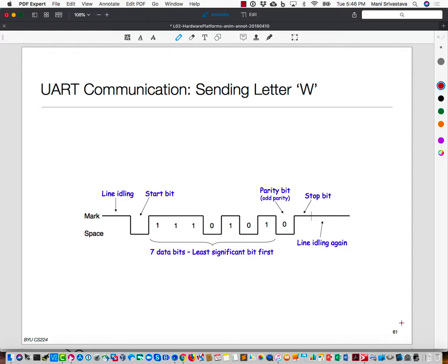So the hardware or software on the receiver is continually monitoring the line. When it sees the line go low, it says, aha, that's the edge, and then it starts sampling at a particular rate. If you want to be really accurate and say it's possible that my clock is not entirely right, then you might also measure the gap somehow, but that's not possible here because the idle is 0 and the first bit is 0, so I won't even see the edge.